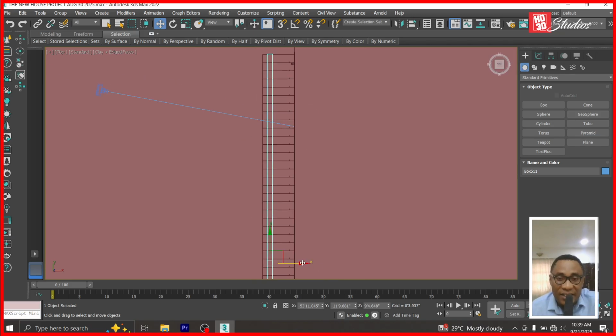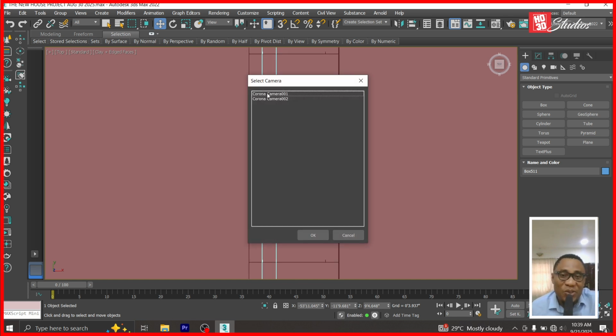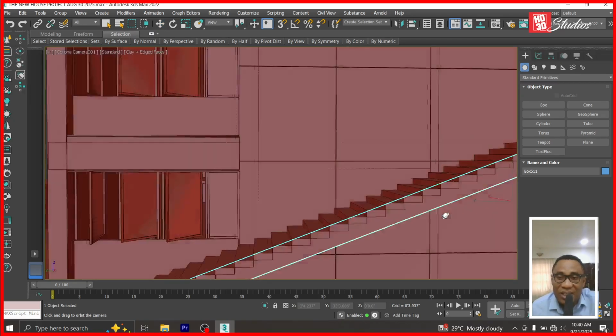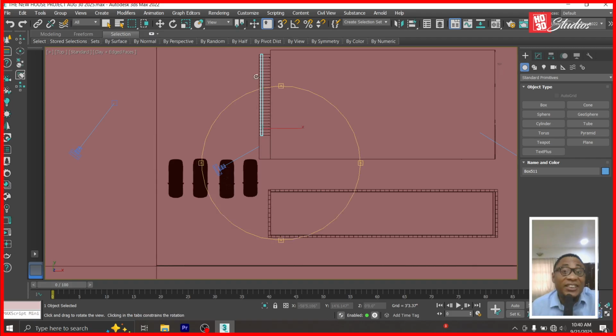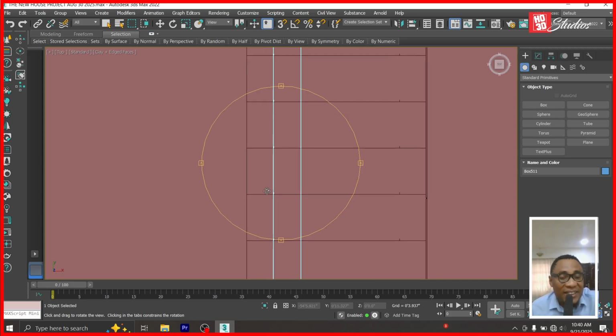So this is the beam now, you can see. Before, the beam was here. It was flush with the stairs. But now, it has receded. So the idea is just to let the jagged edges of the staircase be visible. It's just aesthetics, that's all. I'm sure most structural engineers will, in fact, prefer that the beam is flush. Because right now I've just created a 9-inch cantilever on all the stairs.